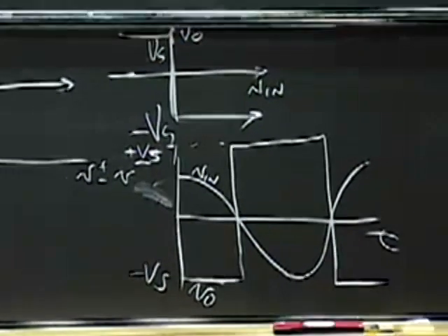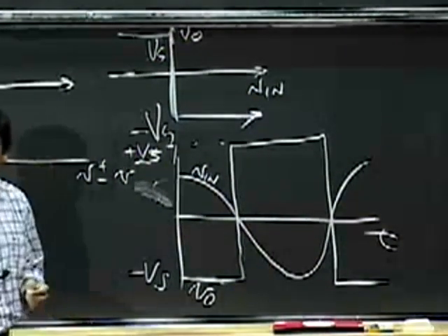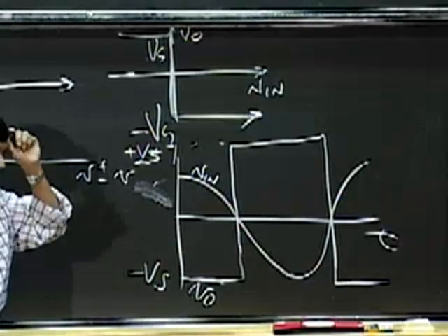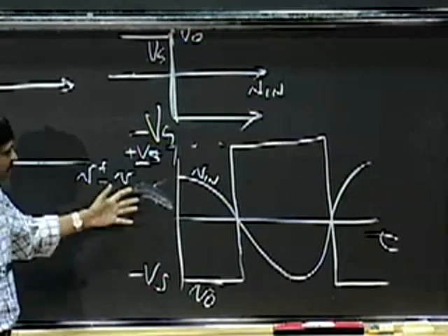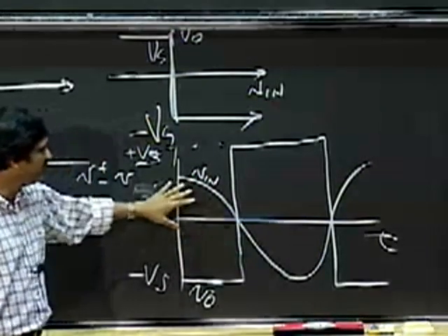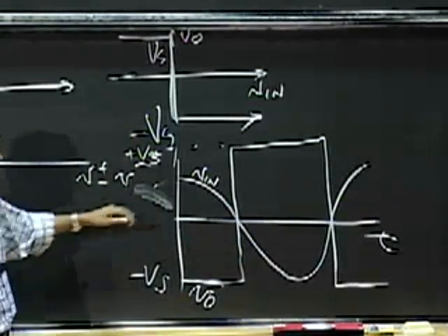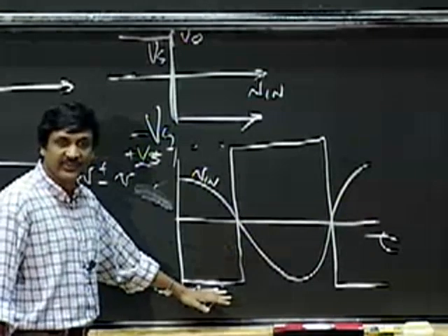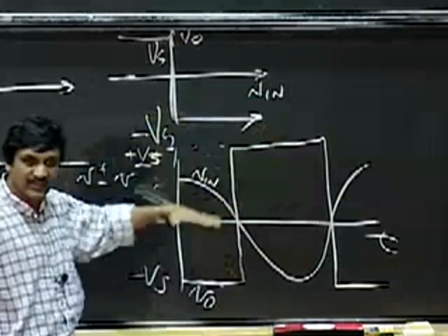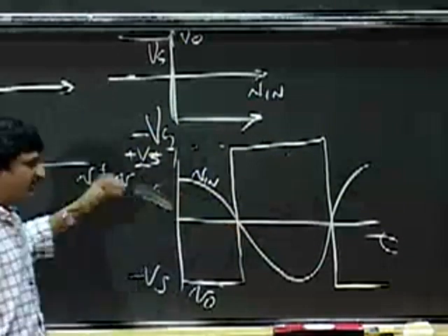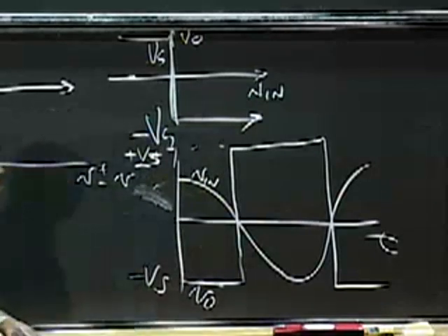So that's quite nice. And such a circuit is pretty useful to me. Let's say, for example, I want to build a little digital circuit that is fed ones and zeros. So I can use a comparator to turn my V in voltage into a sequence of ones and zeros. When V in is positive, I produce a 0. When V in is negative, I produce a 1. So I can get this 1, 0, 1, 0 sequence coming out corresponding to the values of V in being greater or less than 0.